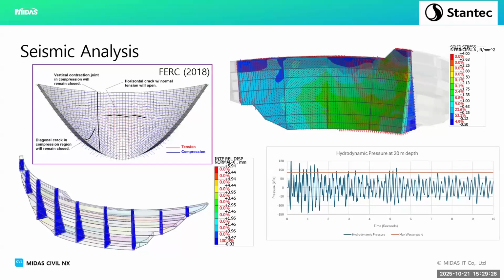So to review this, knowing what we want to do, we've already modeled the dam with interface elements. There is a shear key in there. What's nice with the interface elements is you just leave the shear strength elastic and check it afterwards. The normal stresses you can do as elastic, perfectly plastic. Generally, I put the tensile strength at a nominal 100 Pa or 1 kPa. It's not a massive deal. It converges quite nicely.